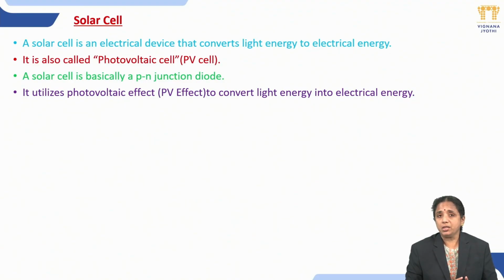But in a light emitting diode, when connected in forward bias and made of compound semiconducting elements, the recombination of electrons and holes at the depletion region gives light photons as output. And in the case of a solar cell, we consider doped semiconductors, not pure germanium or pure silicon, connected in reverse bias. When light energy falls on them, it converts into electrical energy.